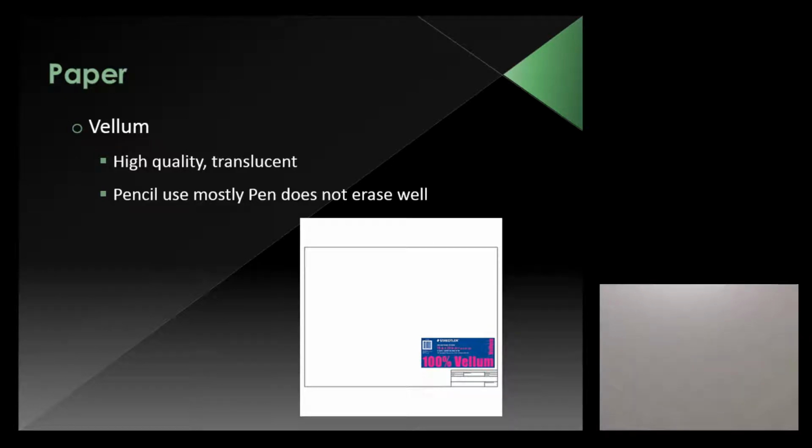I've got my little handy dandy design box here. Let's get a little bit of whiteout tape. You can put that on the vellum, because you're going to take that and get it photocopied. You're not going to run it through a blueprint machine. They're going to scan it in, copy it, and give you a photocopy of your drawing, and this won't show up. So if you do make a mistake and you like using pen, you can use the whiteout.